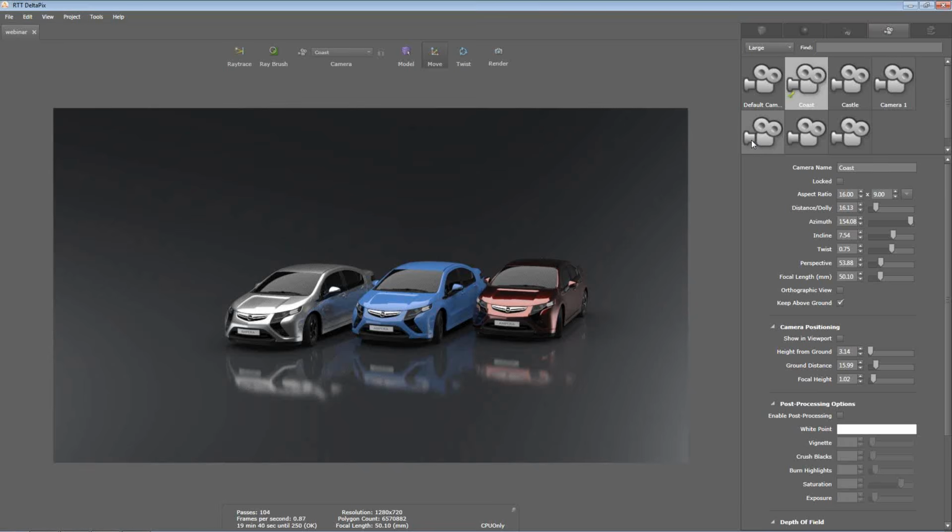A question by David Wong, can you adjust the car's shadow to be lighter or darker? Yes, you can do so. This is going into more of the tricks side of this, but you have two ways. The first is to add, for example, a ground plane below the car and change the material of the ground plane to make the shadow appear darker, for example, or even lighter.